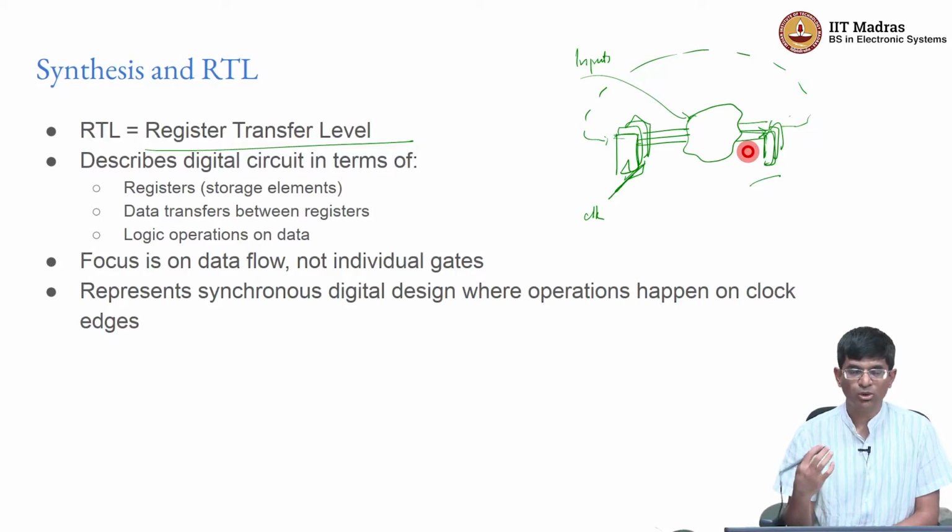So the most important part of this entire course, that I would like to stress again and again, is that it's not about whether you can write syntactically correct Verilog code which will pass a simulation. That is for the most part irrelevant. What matters is, does the code you write correspond to an actual piece of hardware? And for that you should be able to explain it in terms of a register transfer. You should be able to say what the storage values contained within the system are, what computations are being performed, and how this register transfer actually occurs in practice.